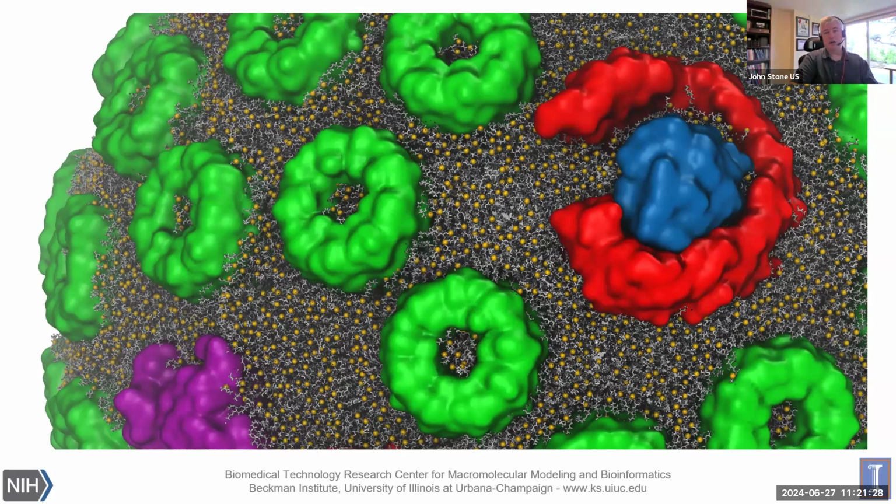So this is a case where there's a little bit of a threshold. The main OpenGL display does very well for run-of-the-mill 100,000 atom structures, but as you get into the many millions or hundreds of millions, the ray tracing renderers start to become more interesting. And in the context of the next version of VMD, something that exists in a prototype form is a real-time ray tracing version of VMD where the entire user interface in the main VMD viewport is done with ray tracing rather than with rasterization.